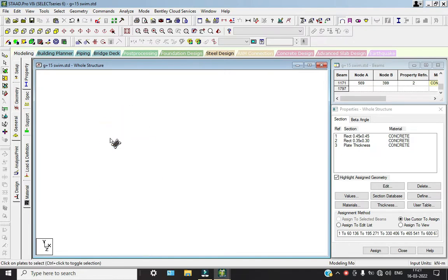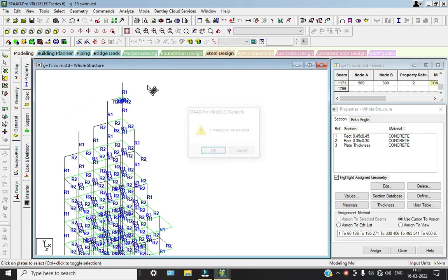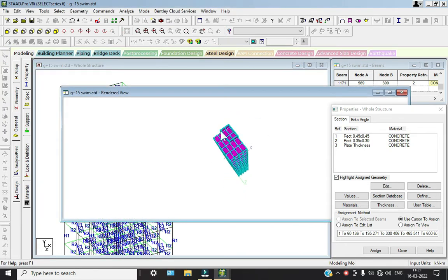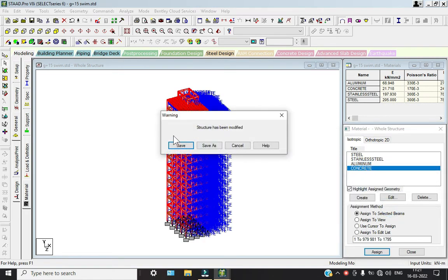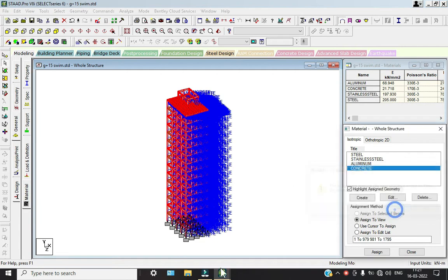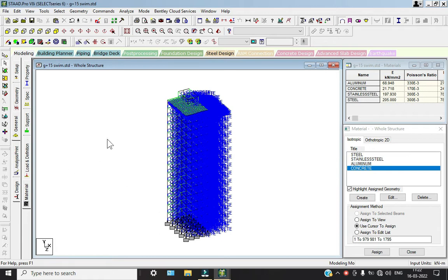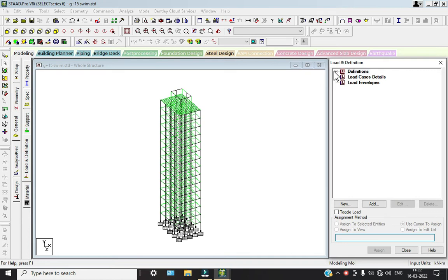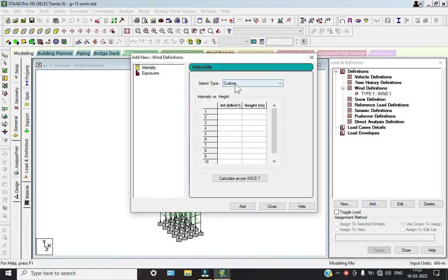Now go to load cases, add, take dead loads and live loads. We're going to take wind loads, WX and WZ, right? So select the dead load, click on add and add the self weight. So now we have to calculate our member loads. For that, open our calculators. We have taken a section of how much? 0.45 into 0.45 into 25. How much? 5.0625, minus 5.0625. Click on add.